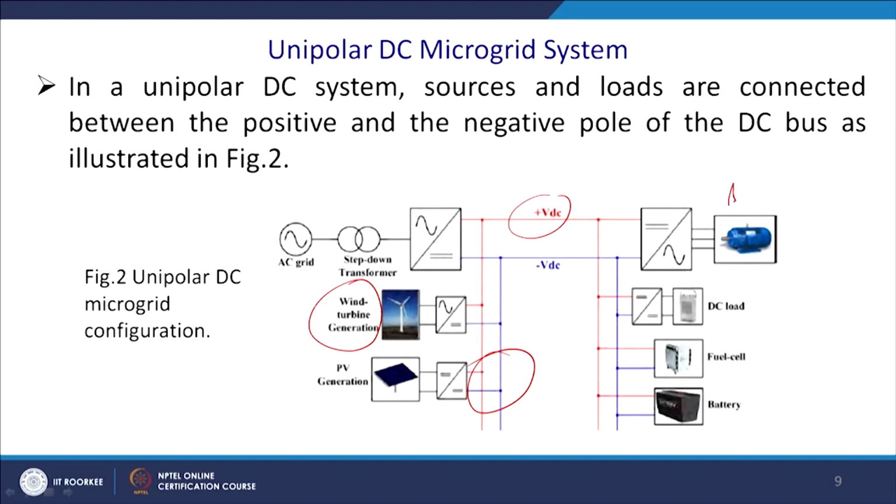These are your AC to DC applications. It may be an adjustable speed drive, so you can apply V/f or vector control for better efficiency and better utilization of the torque. You may have a DC load, such as LED lighting, and you can bypass different kinds of entities. And this is your fuel cell. A fuel cell generally transmits power, so power will go to this bus, and also you have a battery that will be bidirectional.